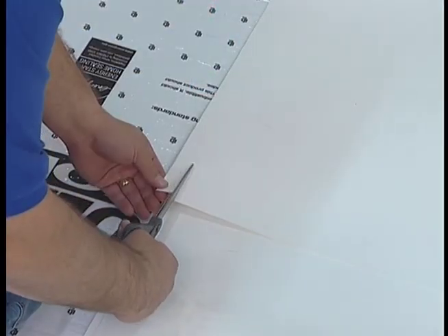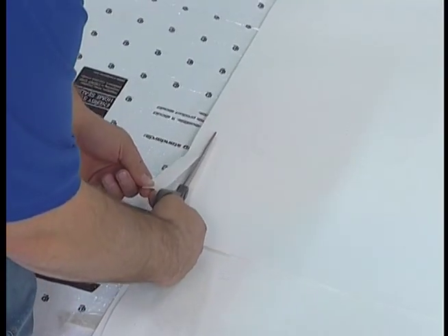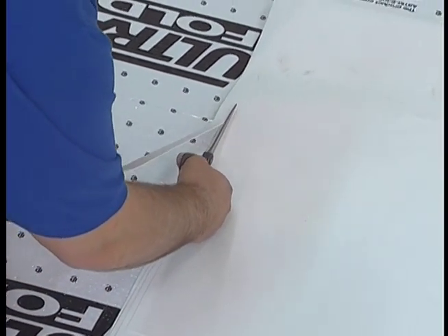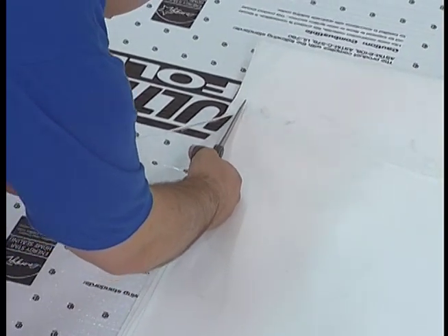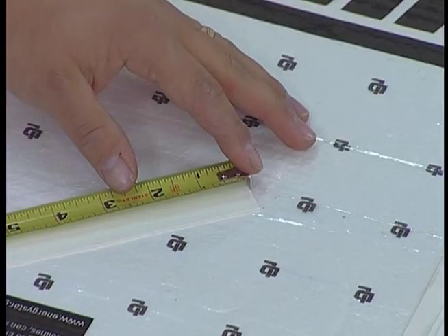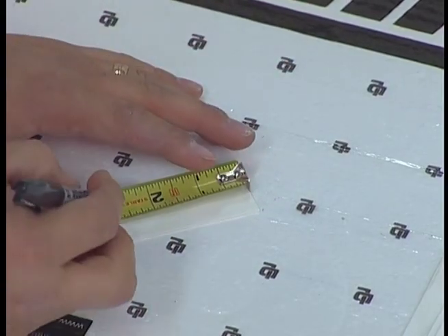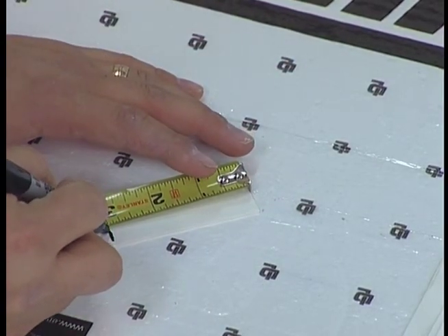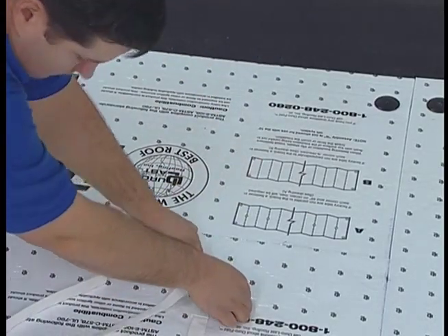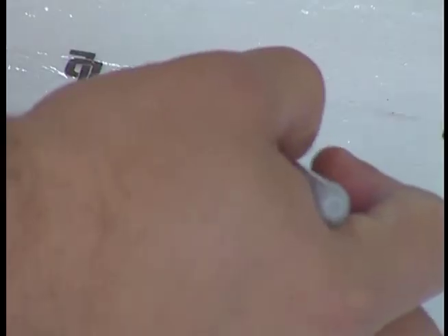For the second method of locating the snap line, cut a thin strip of membrane from one end of your sheet as shown. Include the reverse lap and the fastening tab. Then you can use a pen or marker and indicate the amount of material that must extend over the edge or overlap onto another deck sheet. You can then position the strip as shown and mark the spot where your fastening tab falls.